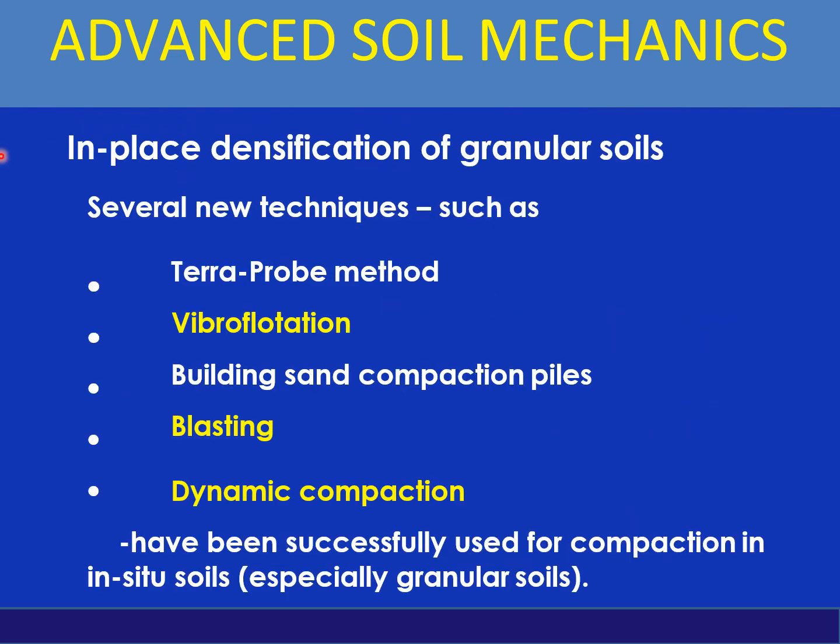Okay, now in place densification of granular soils, several new techniques such as terraprobe method, vibroflotation, sand compaction piles, blasting, dynamic compaction have been successfully used for compaction of in situ soils, especially granular soils.